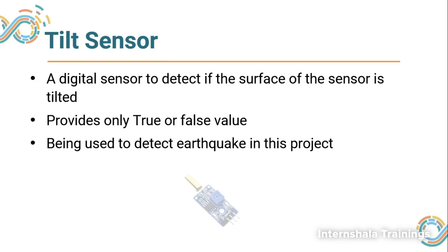Let us see how. This is a tilt sensor, where you can see there is a metallic tube on one end. There is a liquid in this tube, and if it is horizontal the connection between the two pins is not there. If it is tilted, the two metallic pins can get connected or shorted and I can get the output as 1.